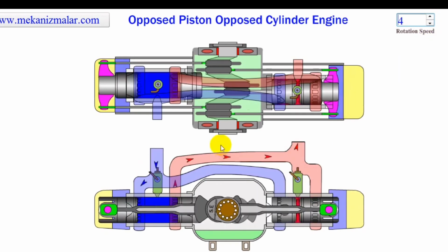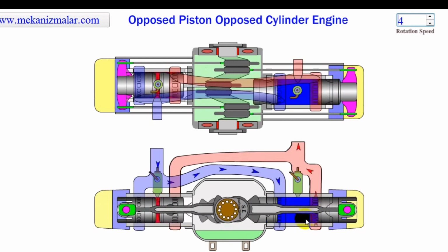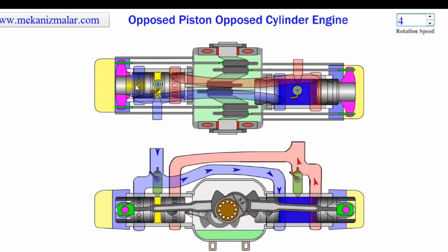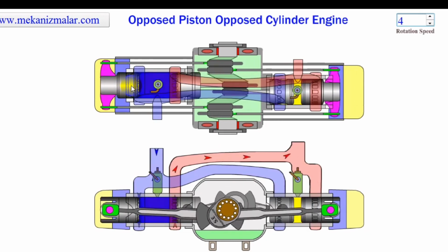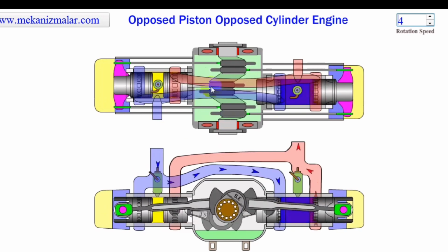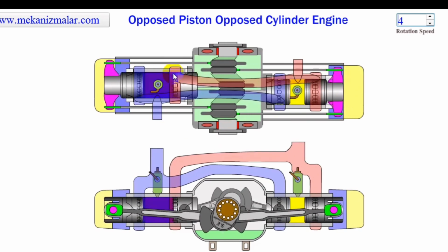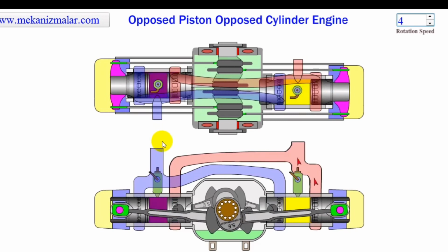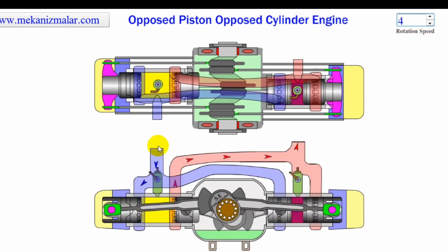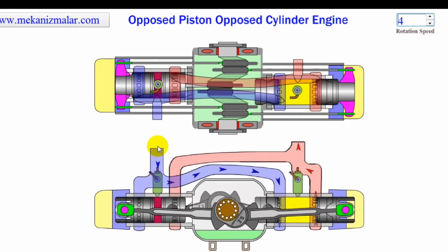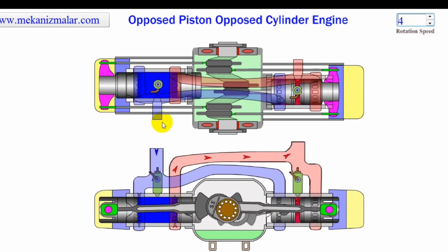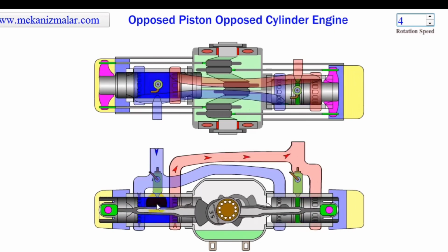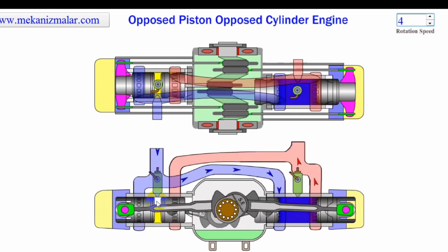The APOC engine is comprised of two opposing cylinders per module, with a crankshaft between them. Each cylinder has two pistons moving in opposite directions. This innovative design configuration eliminates the cylinder head and valve train components of conventional engines, offering an efficient, compact, and simple core engine structure. The result is an engine family that is lighter, more efficient, and economical, with lower exhaust emissions. The APOC engine has 50% fewer parts than a conventional engine, and uses conventional components, materials, and processes.